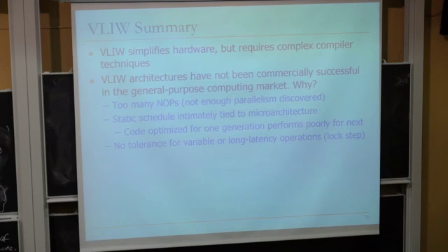The static schedule was intimately tied to the microarchitecture, so again, code optimized for one generation performs poorly on the next. And there's no tolerance for variable latency operations, right? If you get a cache miss, you stall the entire machine. You could do out-of-order execution, but now you complicate the hardware. It's not as beautiful anymore. So you lose a lot of the beauty of VLIW if you want to tolerate variable latencies.